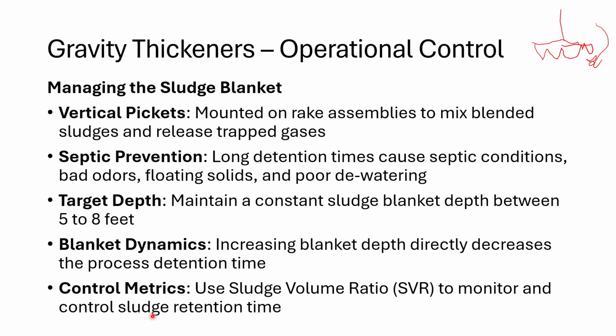Okay, the other thing we're looking at, there we go. We don't want that sludge blanket to go septic. Remember, septic basically means that we're losing our oxygen content. So we're going to form hydrogen sulfide gases, methane, as well as CO2.